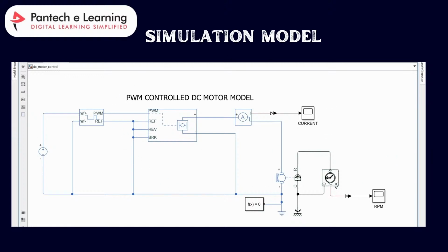Here we are using the PWM method to control the average power delivered to a device, such as a motor or a light. You can vary the width of the pulses in a periodic signal. In simple terms, it's like adjusting the brightness of a light bulb by flicking the switch on and off very quickly.